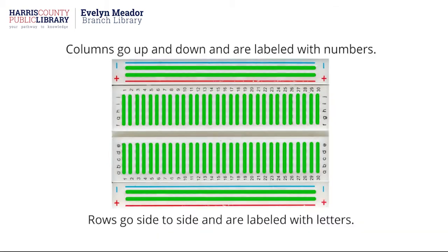This is a breadboard. It's a device that allows you to build circuits without needing to solder them. Each tiny hole is surrounded inside with a conductive metal, and they're linked like this. Each short column of 5 are linked with a gap in the middle. Those are labeled down the side that's on the bottom of yours with numbers. You'll see those 1, 2, 3, 4, 5. There's a gap in the middle, and they are not linked across the gap. So you can see this in this illustration, how it shows the green lines where everything is linked. The long rows on the side are linked